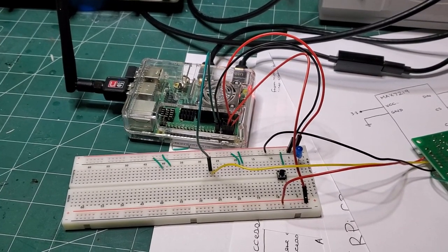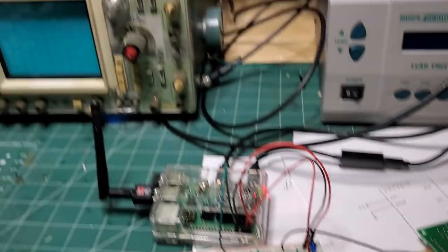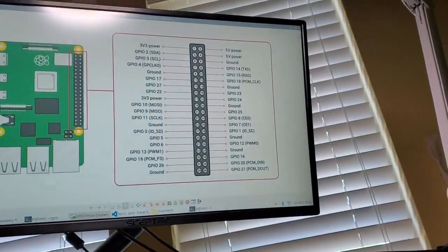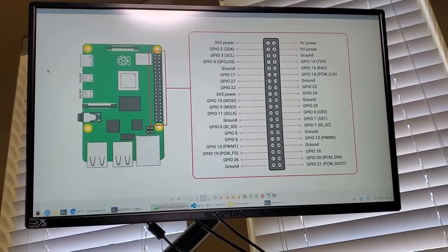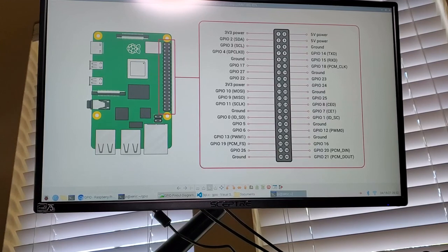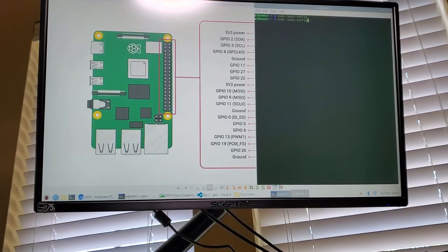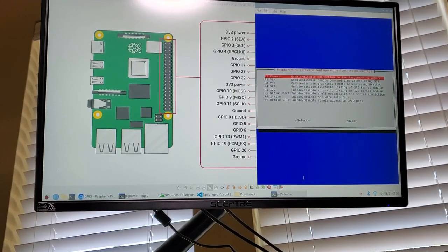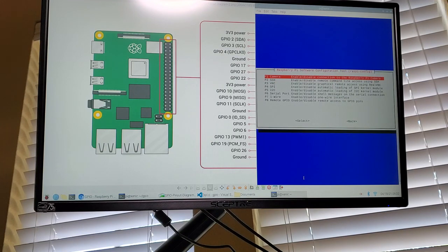There's a couple of things that you do need to do on your Pi, at least if you're running Raspbian. Let me just quickly walk through those so that you can see that. What you basically need to do is go into raspi-config, and then go into interface options. The default behavior of those ports is a command shell, used to remotely log in over serial.